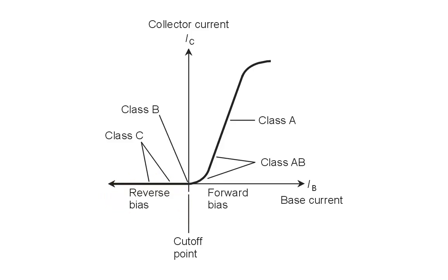So we're going to observe somewhere along in here, in this part of the characteristic curve, 1.5 volts negative on the base. It'll be somewhere around there. Anyway, once again, the correct answer to this question is A, cutoff.